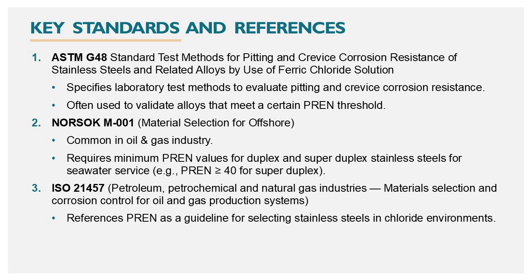Standards and references. Number 2 is NORSOK M001, Material Selection for Offshore, common in the oil and gas industry. It requires minimum PREN values for duplex and super duplex stainless steels for seawater service, for example PREN greater than or equal to 40 for super duplex.